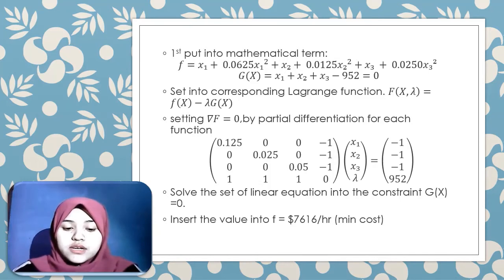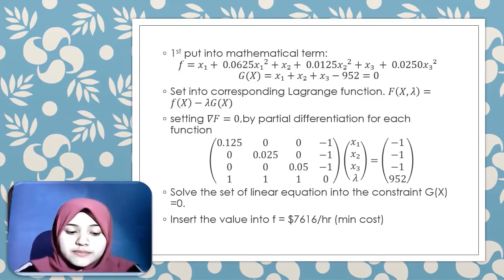The value of lambda is the incremental break-even cost of production that gives the company a price cut for buying or selling the product or generation. If the company purchased generation for less than lambda, then their overall cost will decrease.